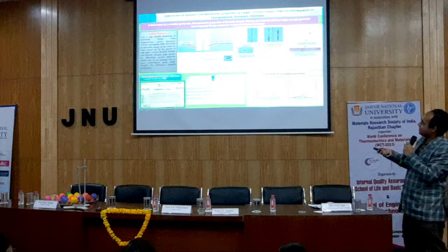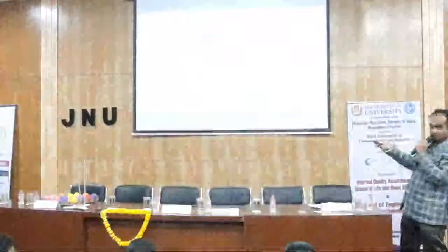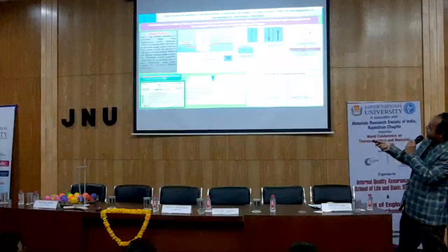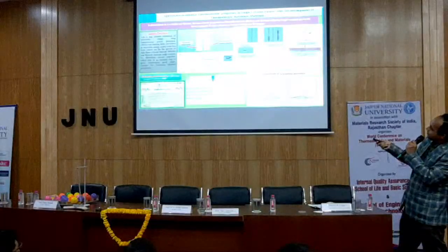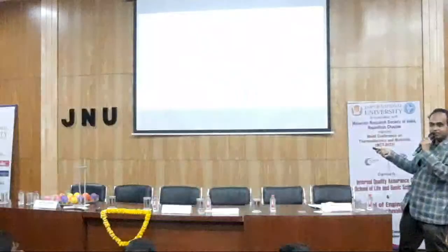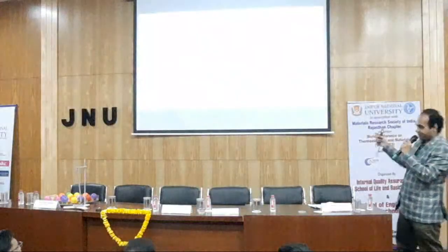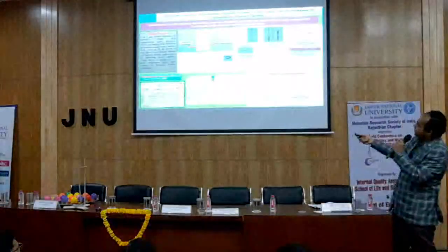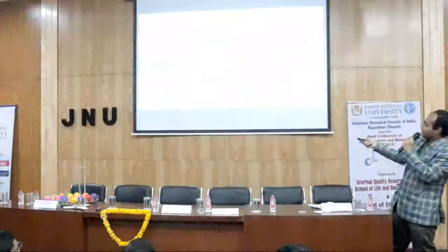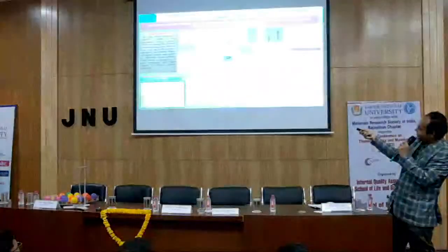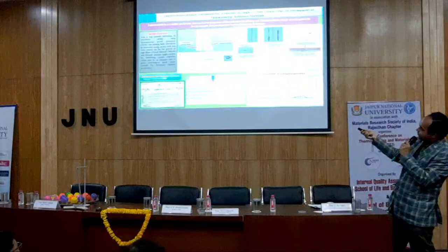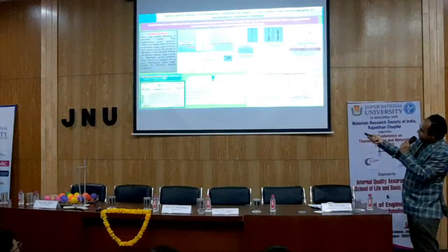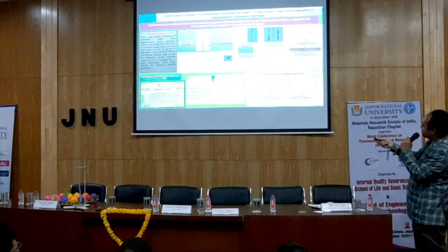This is the conventional approach, and this is what we have done: a bulb-like structure we have introduced. If you see, the crystal grown here will have better quality compared to the bottom, because in the vertical, impurities settle down. First reason is this: impurities go down, so crystal quality is better at the top. Also, if you give a necking over here, the supercooled volume is small. The probability that a single nucleation penetrates from this to this increases. This leads to better quality of crystal at the top, and you can see this one exactly.